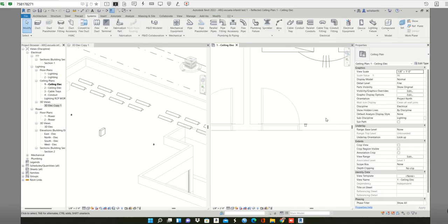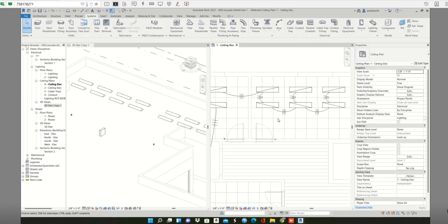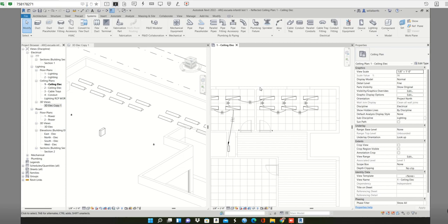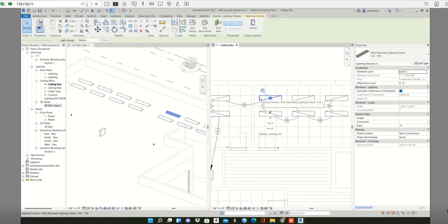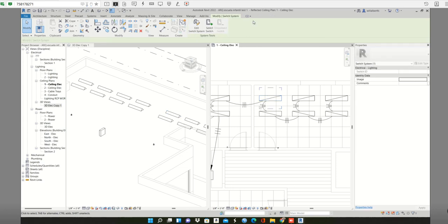Okay, now select again. Yes, select the lighting fixtures and connect them to the switch. Just one, because it's kind of tricky if you do that. Switch, edit, editing. I have to warn you, this option doesn't work. Don't use it. I don't know why it still is in this version of Revit, but this is my enemy. That's why I was trying to do that yesterday, and when I hit select switch, nothing happens. It doesn't connect.